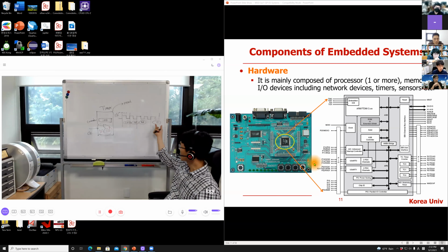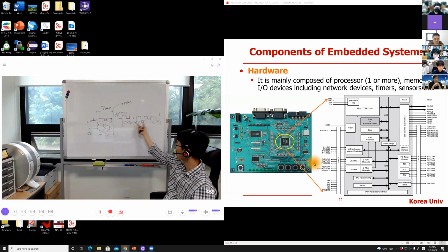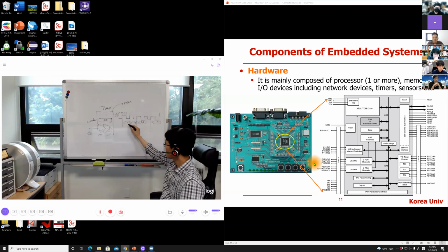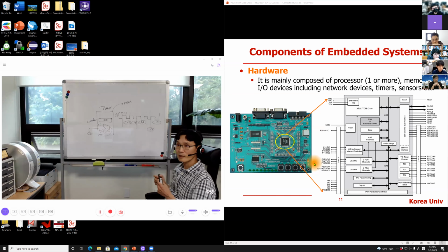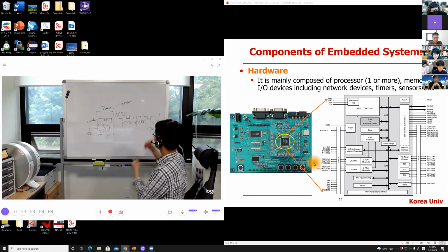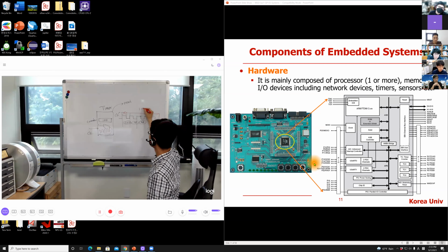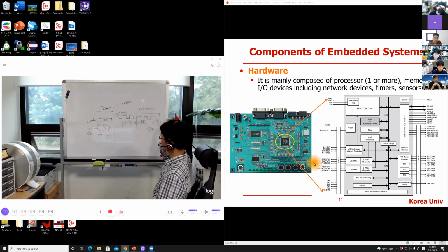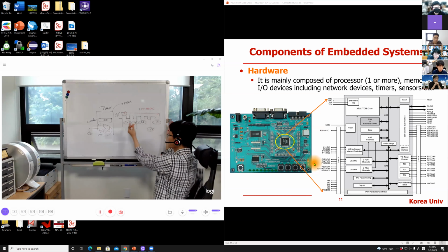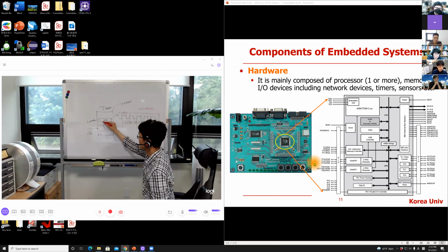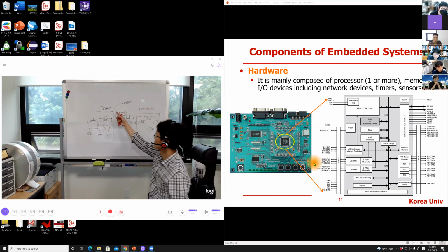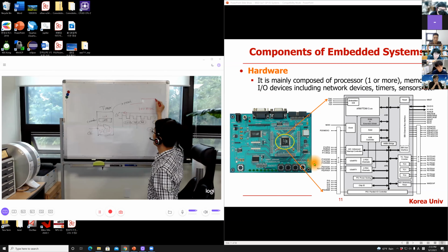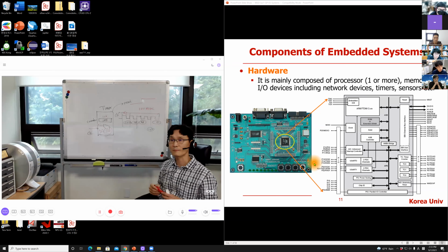So what you have to do is, before this number becomes 0, you have to make sure you refresh this register to 100 again, before this number becomes 0. So this time is something like 100 millisecond, for example, right? So within 100 millisecond, if you don't refresh this register to some non-zero number, then this reset signal will go up to reboot the whole system.